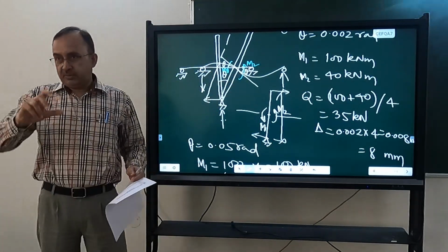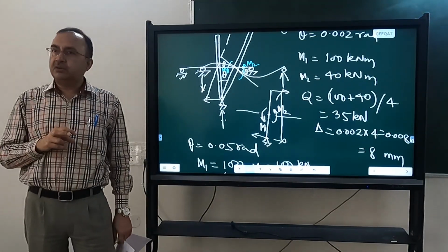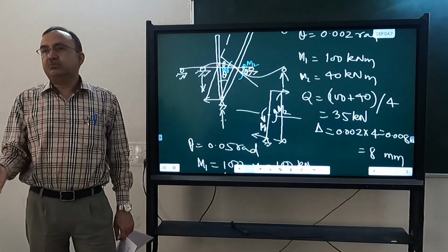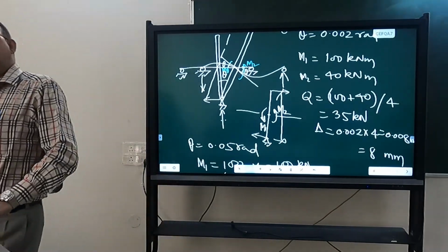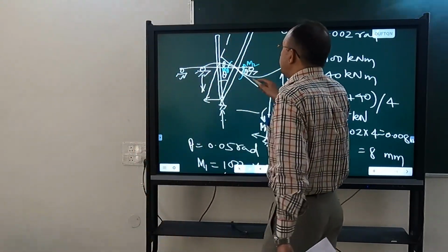For one beam, if you are applying, let us say, same moment, one beam is going to deflect more, another beam is going to deflect less. But if you are applying same deflected shape, same rotation, then one beam will generate less moment, another beam will generate more moment. So where is the symmetry? There is no symmetry. Generating different moments is okay, but deflected shape is same for particular theta rotation. Theta A, theta B equal and deflected shape is same for that. That is not symmetry. Same deflection on left and right doesn't mean that these will be symmetric. Deflection in left and right will be same in any case. Whatever you do, compatibility is to be satisfied.